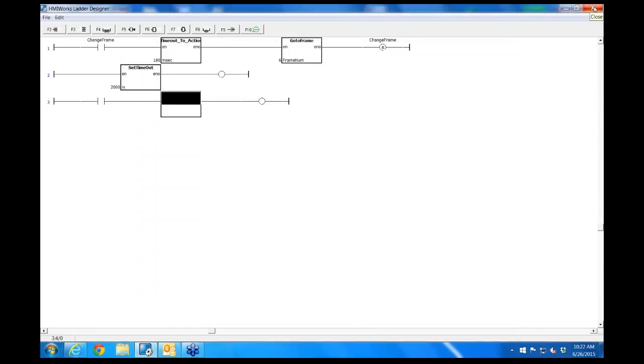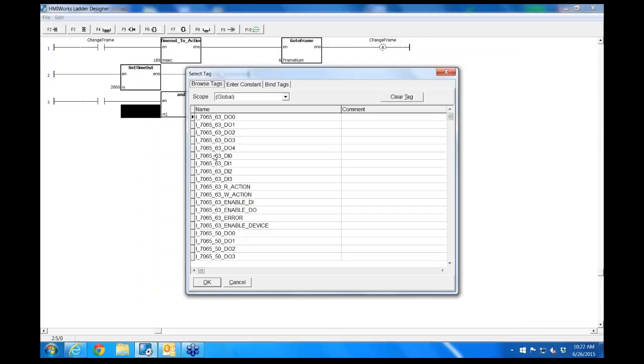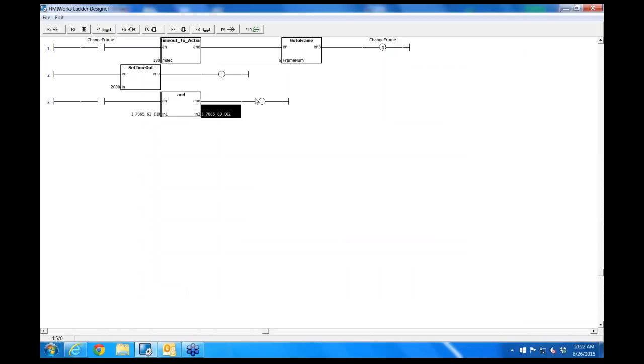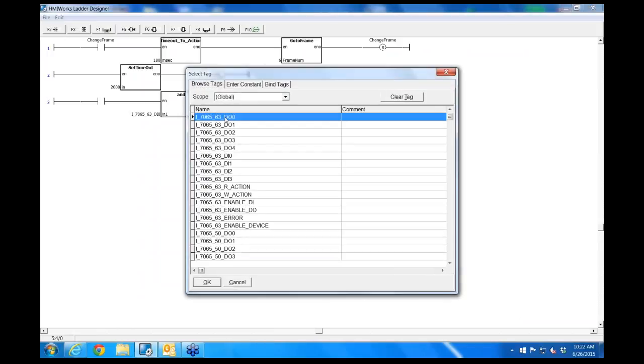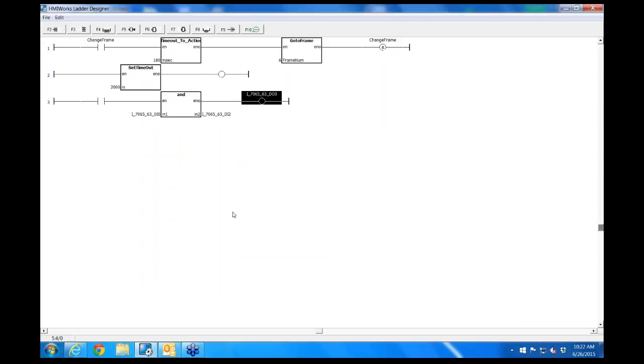So for the ladder logic, you simply create your coils and create your function blocks. Let me just give you a quick example. For an AND operation, if say digital input 1 and digital input 2 were true, then it would turn on a digital output as an example. Just delete that portion by pressing the delete key. So if you need an AND operation for performing an operation, you can do something like that.